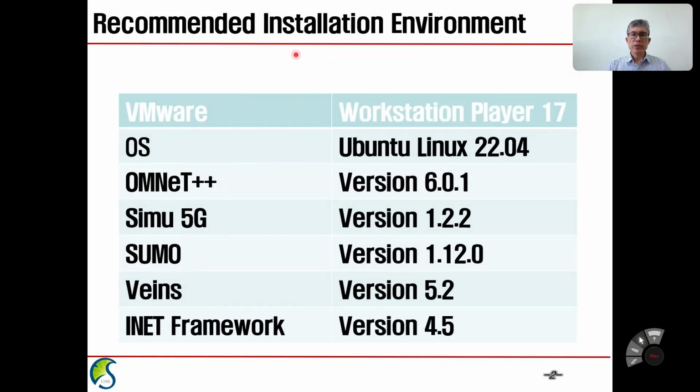The recommended installation environment for simulation with OMNet++ and SUMO: if you use a Windows system or Mac OS as the host operating system, I recommend using VMware Workstation Player as the hypervisor.